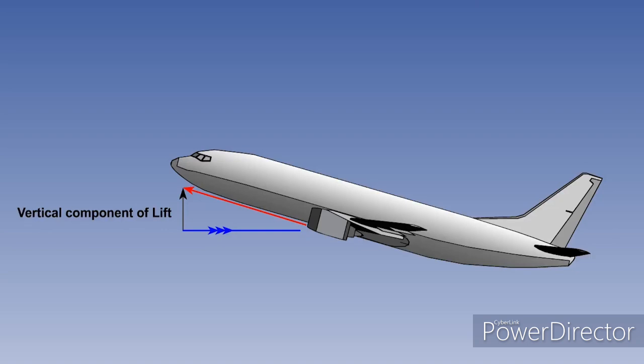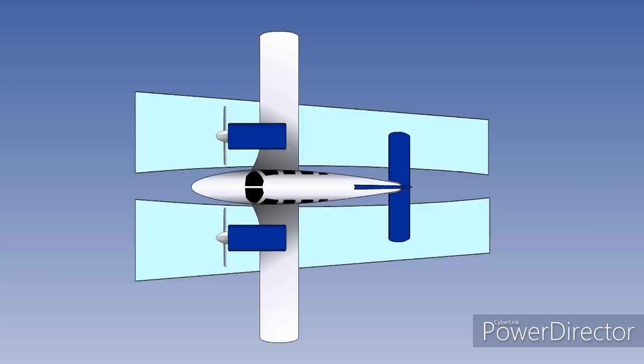Propellers will create an extra effect because of the slipstream. The most important factors in this situation are engine type, propeller or jet, thrust to weight ratio, and the inclination of the thrust vector at CL max. With propeller-driven aircraft, the slipstream velocity behind the propellers is greater than the free stream flow, depending on the thrust. Thus, at low IAS and high power, the dynamic pressure within the slipstream is higher than that outside it, and generates more lift than at zero thrust.